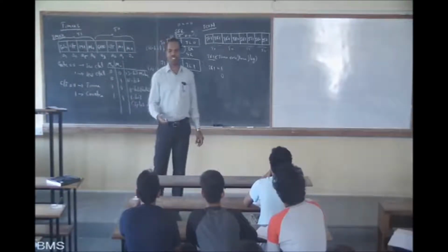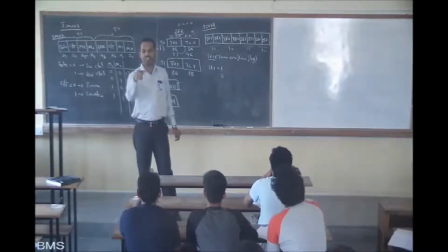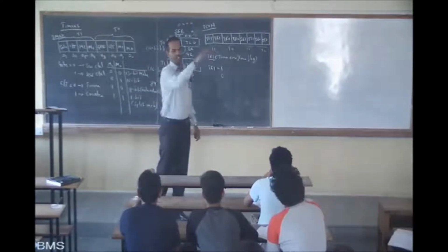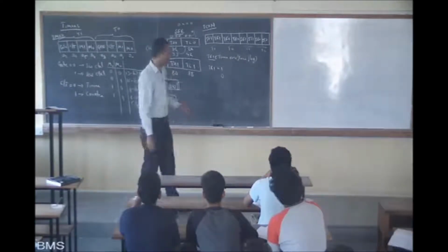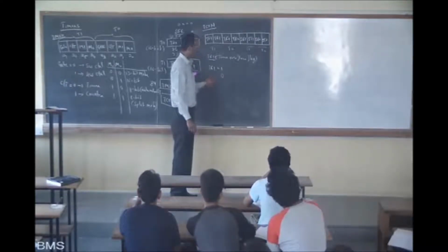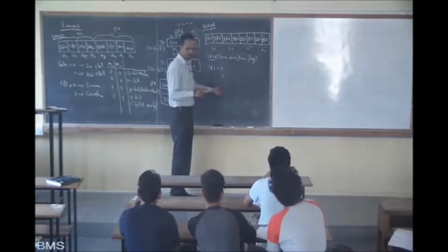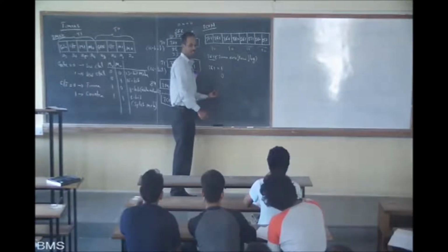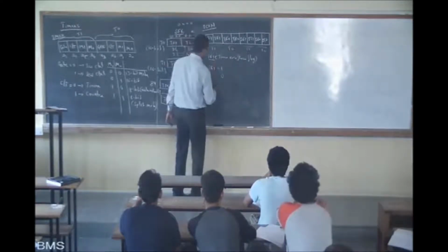No, that I know. Internally what happens? Clock gets supplied to the counter. Till then, it will not be supplied to the counter. How can you think about this? There is an AND gate. For the AND gate, one input is the clock, another input is TR1. If TR1 is 1, then only the clock goes ahead. If it is 0, the clock does not go ahead. Clear? Done. Next one.